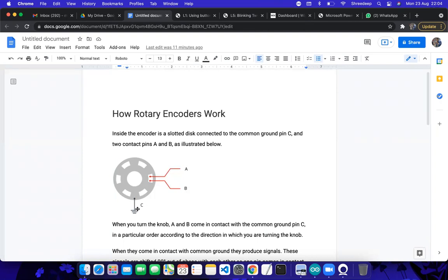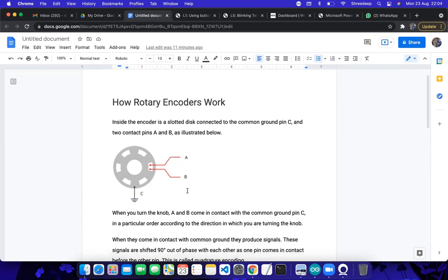If they are, they are not the same. Phase quadrature means either A is leading B or A is lagging. So there will be a phase-shifting circuit inside the rotary encoder. At the back side of the rotary encoder, you see there are 3 resistors, R1, R2, R3, and within this encoder it will have some capacitive element to provide the necessary phase shift. An RC element will provide a 90-degree phase shift. That is why it is also called a phase quadrature encoder.